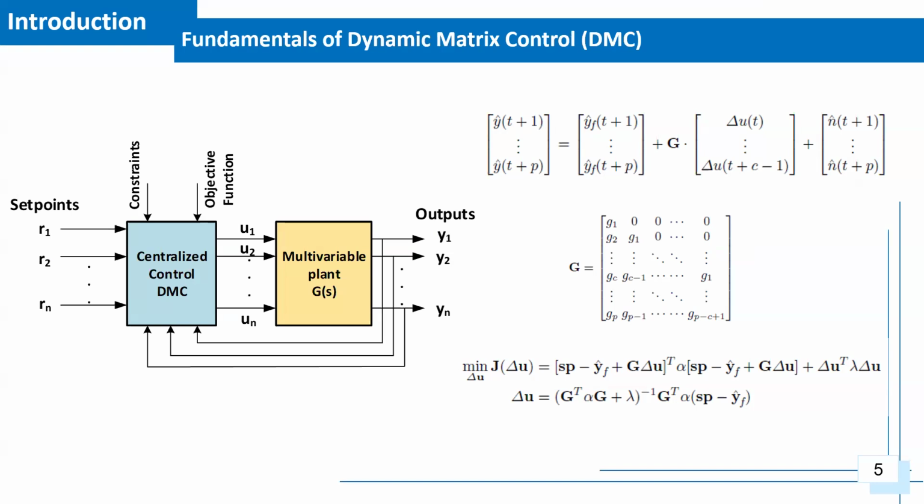One of the most common MPC algorithms in industry is dynamic matrix control, or DMC, mainly due to its simple implementation and strong performance. DMC relies on a linear model of a stable open-loop system, uses the step response to generate the future predictions, and assumes constant disturbances over the prediction horizon. On this slide, we illustrate how future outputs are computed using past inputs up to the current time. The algorithm predicts the outputs across the entire prediction horizon, from time t plus 1 to t plus p.